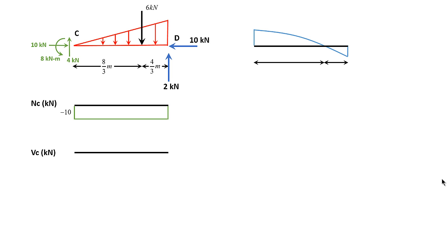And the shear force basically is a result of integrating the load equation. If the load equation is of the first degree, that's x, for example, I'm going to have the shear force be of second degree, that's x squared. So it's not a straight line. Okay, but the problem here is trying to find where the shear force diagram crosses the x-axis.